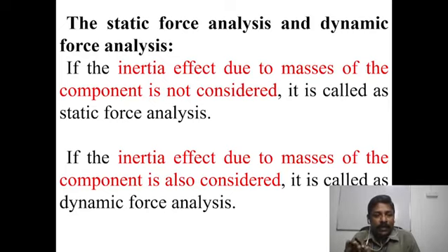Static means the condition of rest, and dynamic means motion, so that is not the basis here. Here we are dividing based on inertia. If the inertia effect is not considered, it is static force analysis. If the inertia effect is considered, it is called dynamic force analysis.